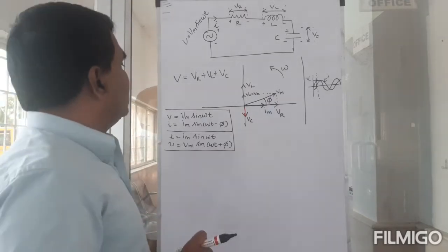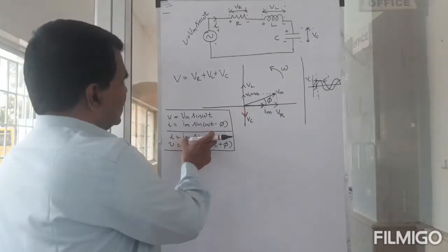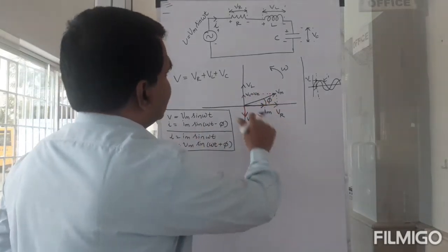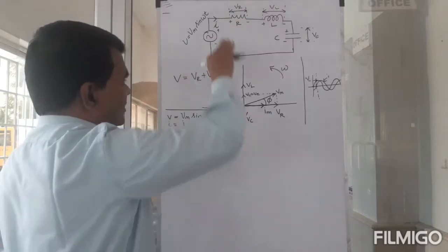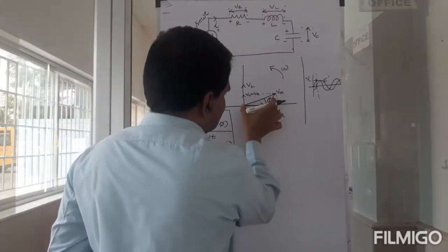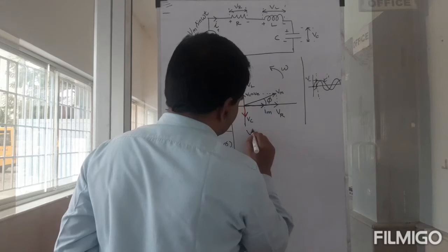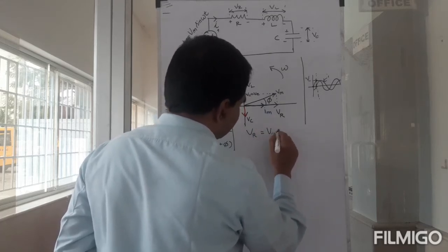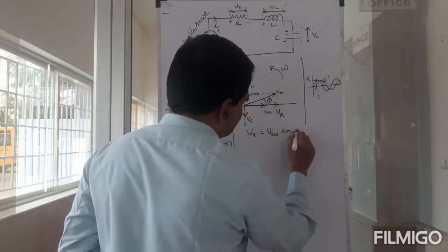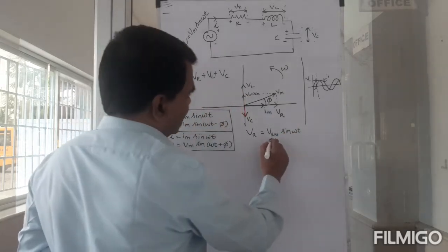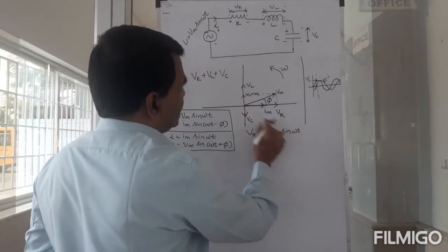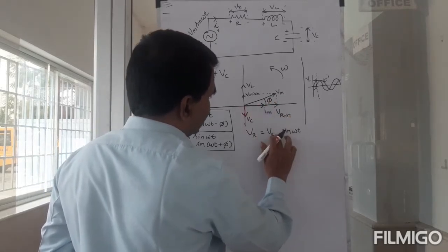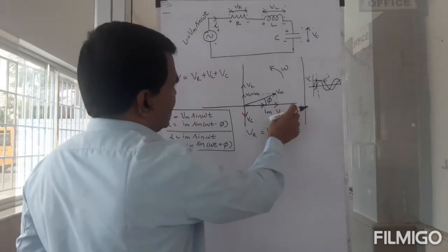And now, if I take Im sin omega t as a reference, then clearly Vr will also be varying with time, right? So in that case, this length, say Vr, with respect to time is going to be Vrm sine omega t, correct? So you will have a maximum Vr here. Okay. So if you take this, that would be Vrm, the maximum value of this.